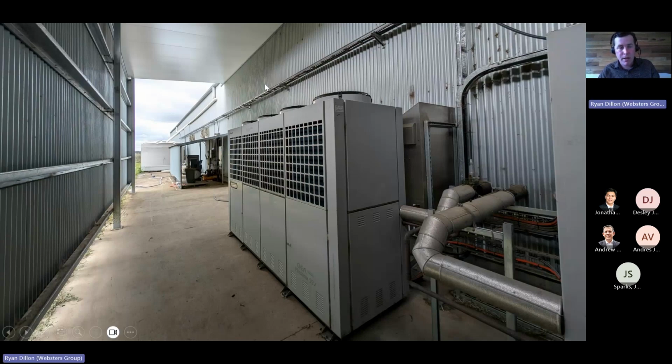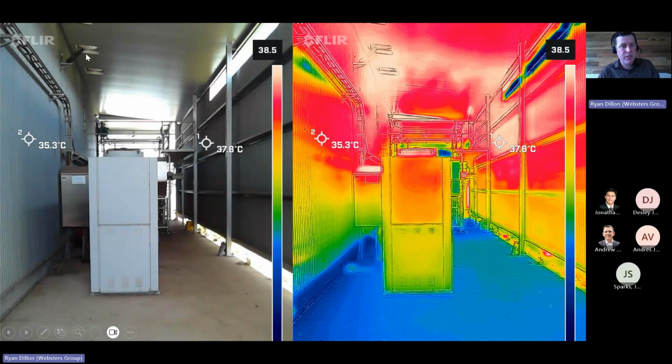So when we run the thermal camera across this, and you can see the fans here to reject heat, there was a purposeful cut in the roof. Despite this, what we're seeing is as that heat's rejected, it is cycling this way. As it pushes up, some of it pushes back down into the condenser vents, and there's a bit more room on this side.